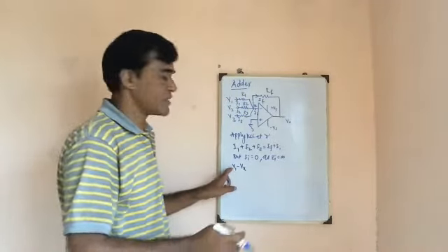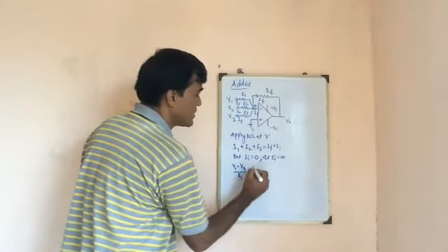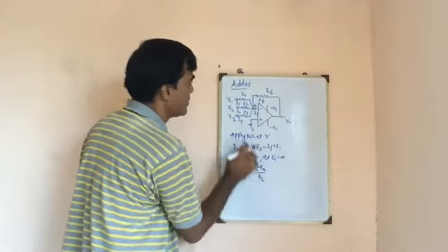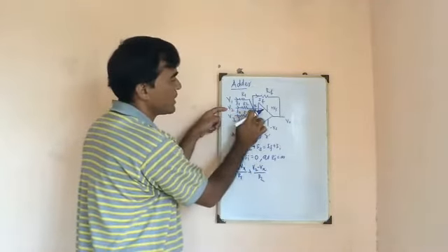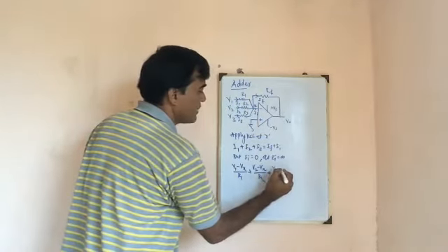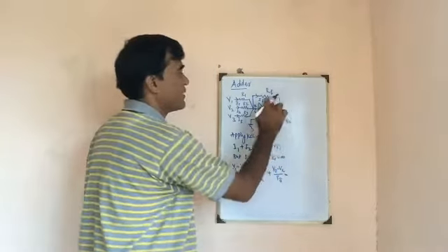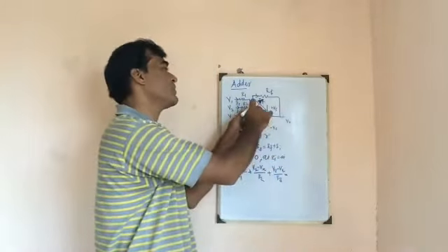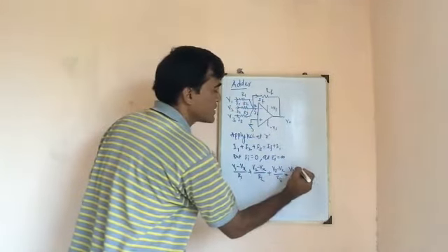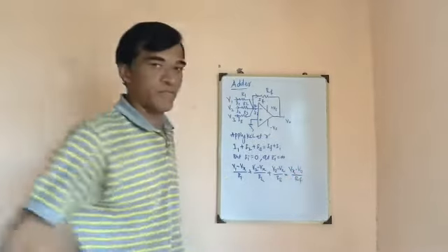So (V1 minus Vx) divided by R1, plus (V2 minus Vx) divided by R2, which is I2, plus (V3 minus Vx) divided by R3, is equal to IF. And what is IF? IF is the current moving from node X to the output. The potential difference becomes Vx minus Vout, divided by RF.